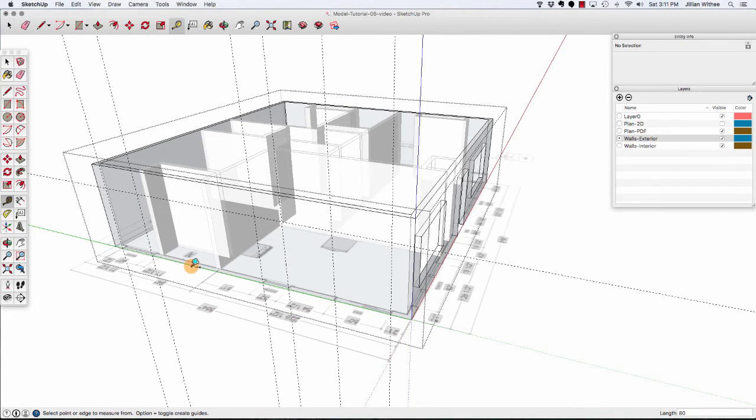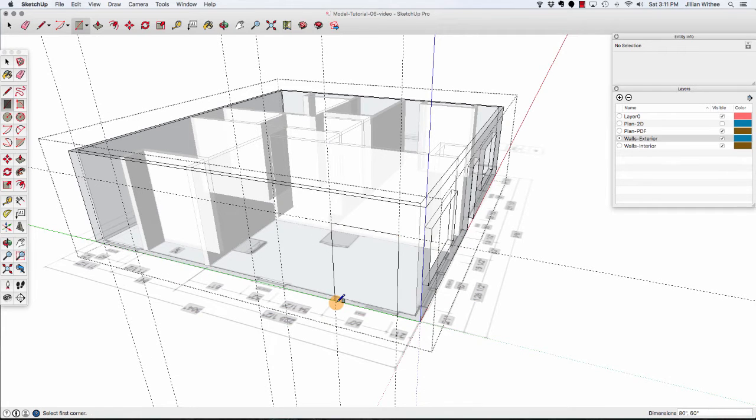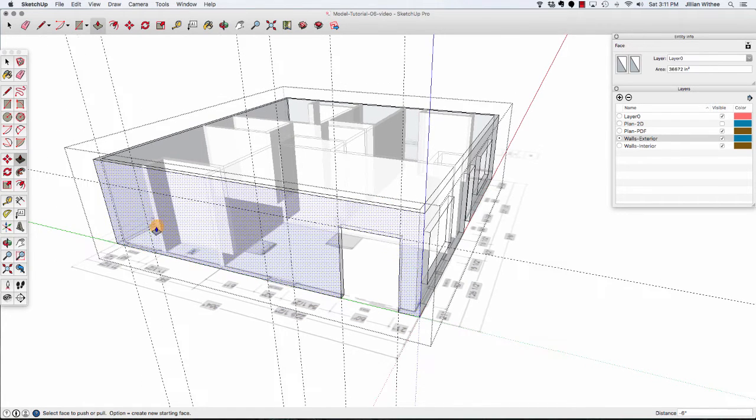And then the sill, let's do the doors first. So make sure you're on those X's. Draw the rectangle for the sliding door. Punch that hole open. And now for the windows, they have two different sill heights.